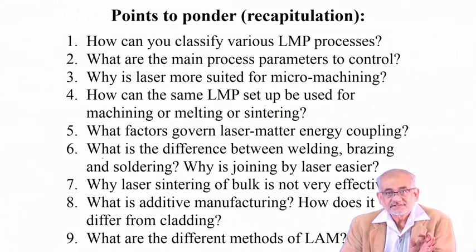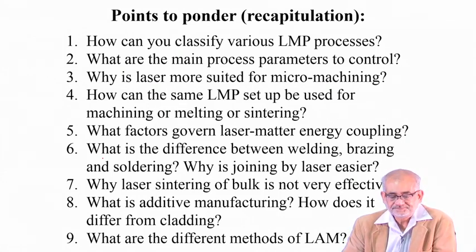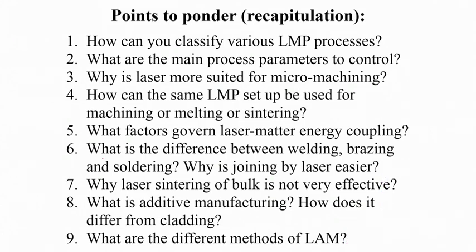So using the same laser, actually by changing the parameter, the power density and the interaction time, you can do either only heating, you can do sintering for that matter, you can do melting, solidification, you can do even machining with or without carrier gas like oxygen. The surface condition is very important in terms of efficiency of coupling the laser matter, and also the wavelength, the various material properties like the density, the melting temperature, the specific heat, and so on and so forth are also very important.